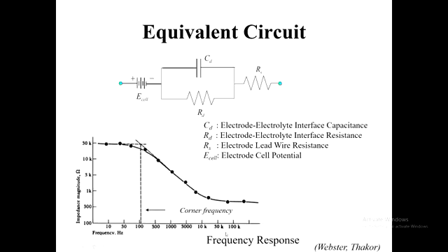However, they are useful not only for voltage transfer functions, but here we've got an impedance transfer function in terms of frequency on a log scale versus a log scale, damn it. And you thought you were getting away from it. What this is meant to show is at low frequencies, the resistance is quite high when this shunt capacitance, shunt across the interface resistance, is acting